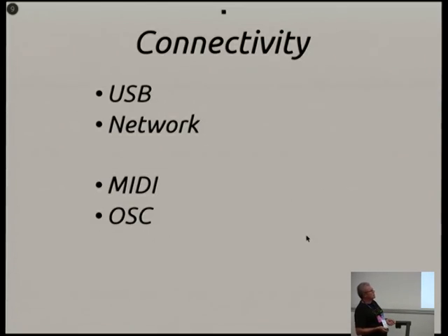And the two equivalent technologies that map to those are MIDI and Open Sound Control. MIDI is traditionally a serial port type-based protocol, but most MIDI adapters now are USB adapters. And the MIDI spec does actually have a proper USB device class in it. Open Sound Control is pretty much Ethernet-based UDP packets over the network, can work over wireless, can do pretty much anything. We're not really trying to do proper music playback, it's more control. So we're not worried about 10 millisecond latencies. It can be a little bit slower.